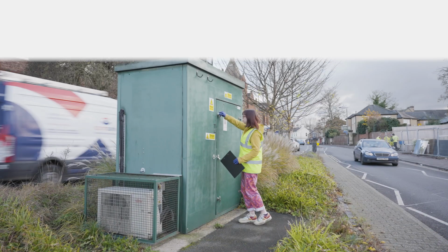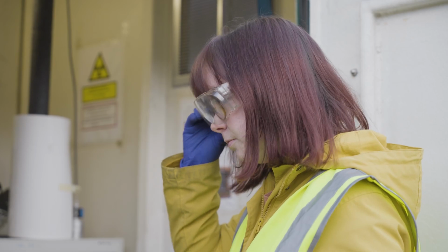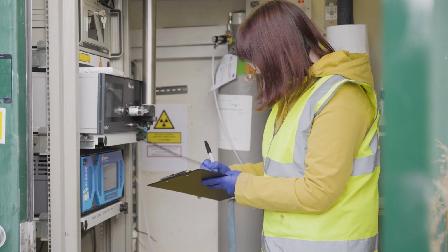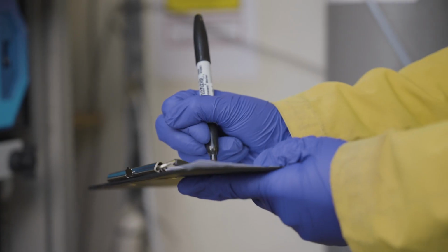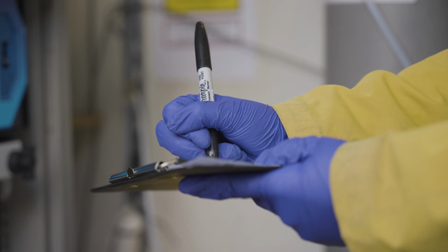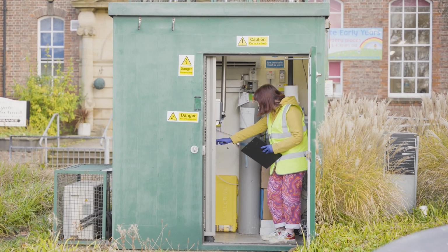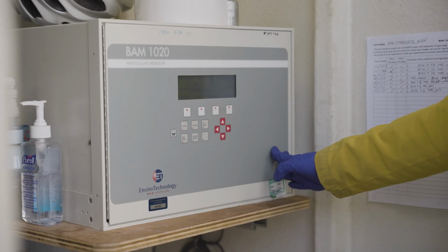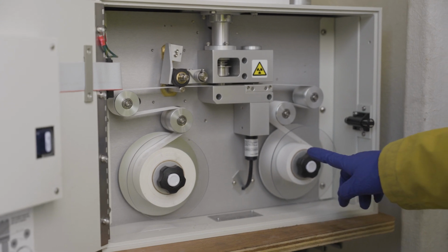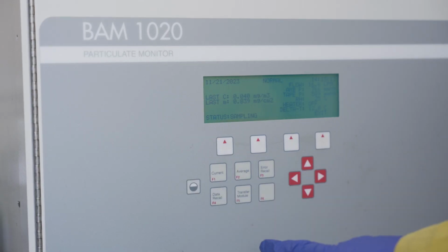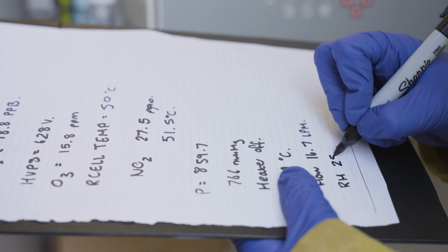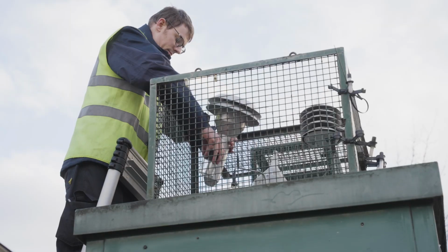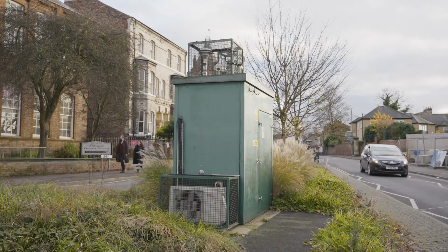For longer-term and larger-scale monitoring studies, depending on budget and resources, you may want to use an automatic sampler. These can be used to take consistent measurements over time to capture temporal trends in air pollution. This equipment is able to take real-time measurements of various air contaminants, including NOx, ozone, particulate matter, and benzene, as well as environmental parameters such as temperature. Whilst this method can provide high-quality data, sampling stations are usually fixed and expensive to set up and maintain, which may limit the number of monitoring locations in a study.